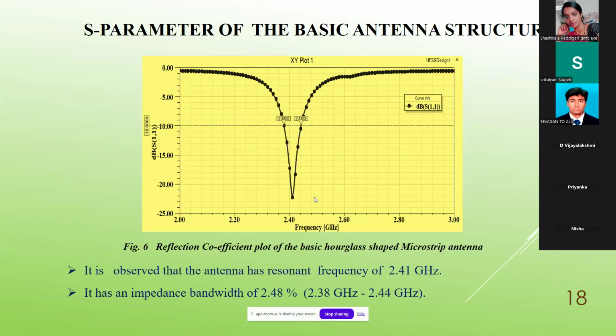So first of all, when we go for simulation, we should check whether S11 is achieved correctly or not within our operating band. That is very important. If you are achieving the S11 or reflection coefficient as per our requirement, then we proceed further. Otherwise, the design has no meaning. You can see we always consider the minus 10 dB line because it is related to return loss.